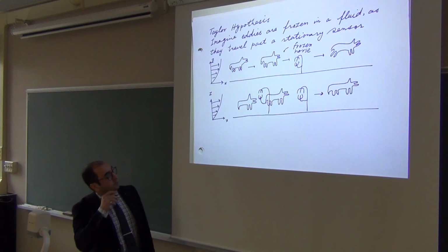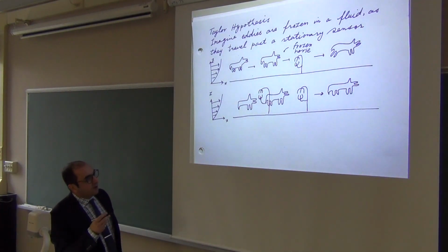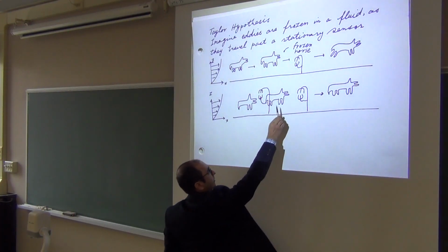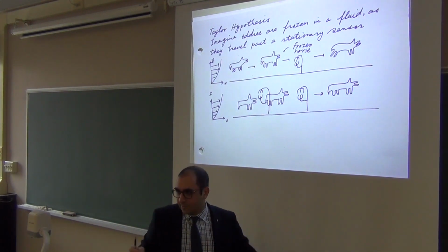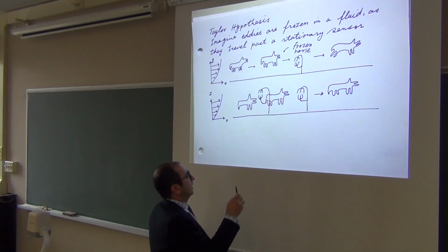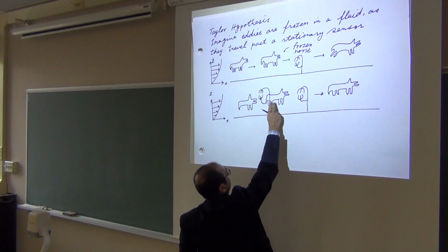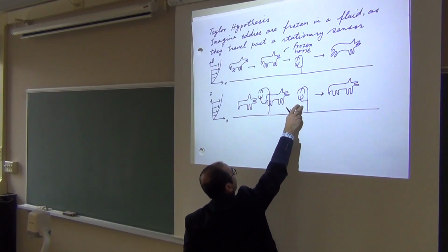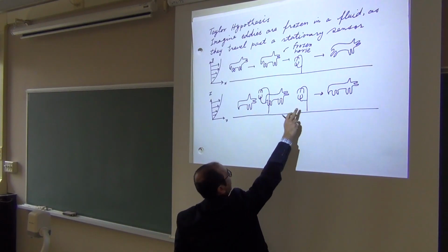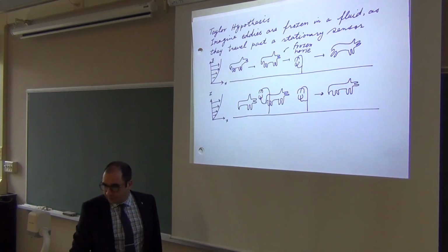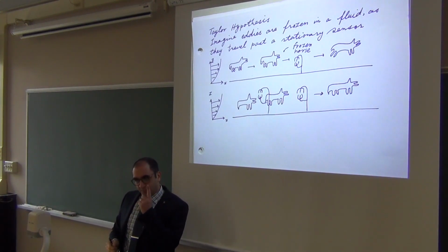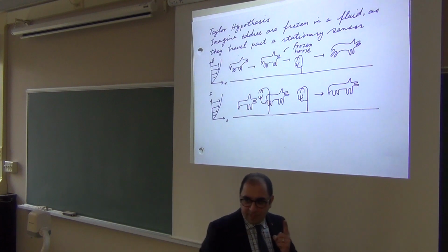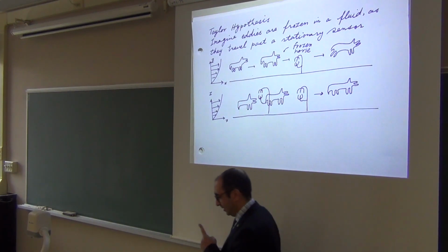Why am I saying this? Because if I want to measure the nose and the tail simultaneously, I need 2 sensors. These are the 2, and the 2 measure here and here, right? But if the eddy is frozen, I don't need 2 sensors, because I can measure the nose and then just wait until the tail goes past the sensor, right?